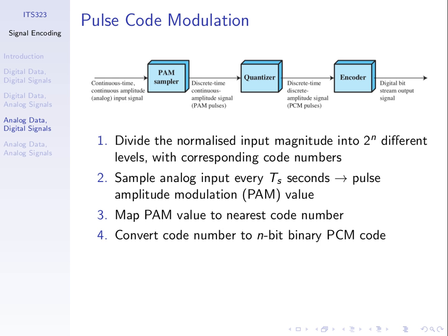That's a good thing. But if we increase the samples per second and the code numbers, the number of bits that we need to store or to represent that analog data goes up as well. And we saw an example where we had 3 cases yesterday where we varied the sampling period, or decreasing the sampling period increases the sampling rate, and we varied the number of levels or code numbers. And we saw the impact that it had on the data rate required.